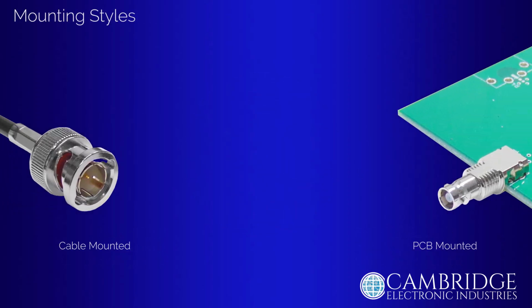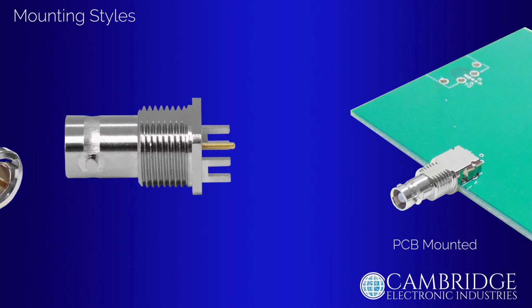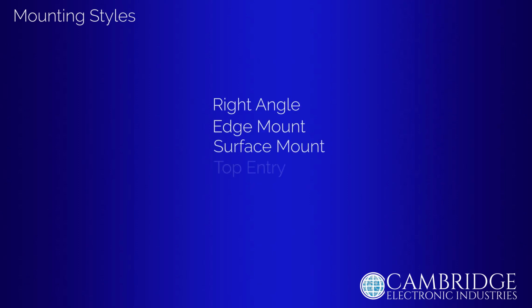Coaxial connectors are available for both PCB and cable mounting. PCB mounted coaxial connectors will have a centre pin that either sits on top or goes through the board and solders to the signal trace. The outer shell usually has multiple solder or press fit legs that connect to the PCB ground plane for mechanical stability and electrical shielding. There are 5 main PCB mounting styles. These are right angle, edge mount, surface mount, top entry, and end launch.